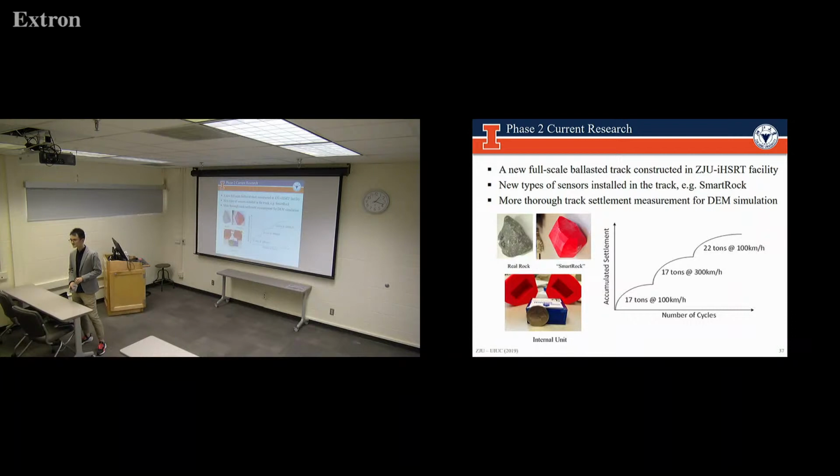Can't we look at it from the perspective of stiffness, like the intelligent compactor? Let's suppose we check the stiffness, then we can put in a certain air void and quickly check the stiffness. Do a deflection back calculation. I mean the deflection, not necessarily the stiffness. You can check it from this model for a certain percentage air void, or you can do sensitivity analysis for parameters that might match whatever deflection you get from there.